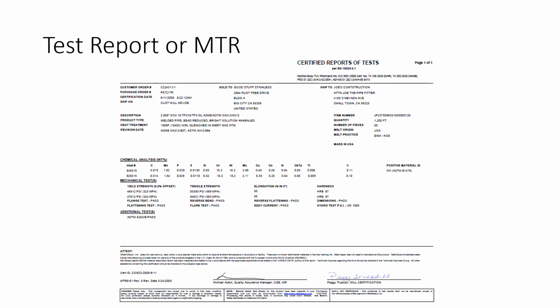Product manufacturers, such as a tubing manufacturer in this case, will in many cases transpose the data from the mill's test report onto their own MTR form, which is what we have here. The properties, both chemical and physical, have to be within the ranges, minimums and maximums specified within the chemical recipes of ASTM and other accredited standards organizations. The MTR is a means of verifying and noting that fact.